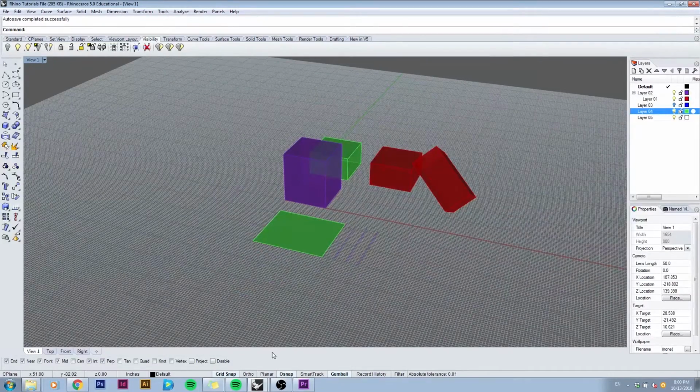Now, let's talk about snapping. Snapping are these modeling aids that assist with moving your objects and clicking around your model. They are incredibly important in aiding you to create accurate models. They basically snap to important parts of your 3D model. They are located at the bottom of your window. To turn any of them on, you simply click on them, and they will turn bold.